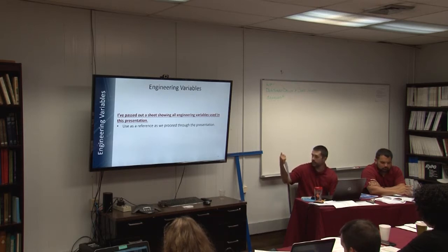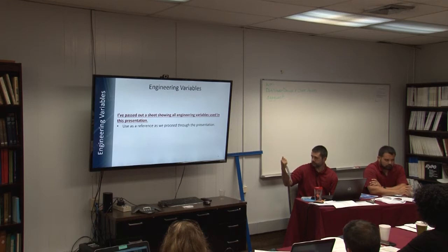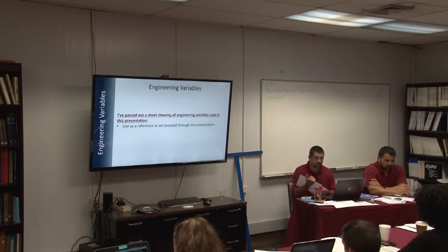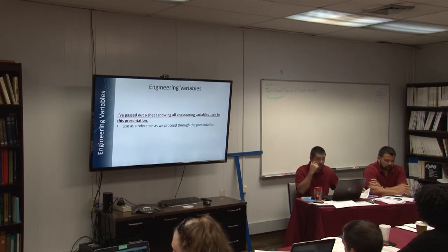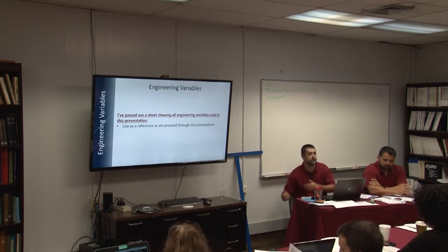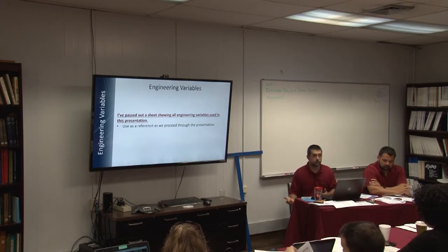PLS Tower is checking 6 limit states for you, and they're listed across the top. There is net section, rupture, and block shear. Those are tension limit states. Bearing and bolt shear are tension and compression limit states. And then buckling, or L over R, is a compression limit state. What we're going to focus on this afternoon is those 6 limit states, the calculations that the code requires, and how you get PLS Tower to do those calculations for you in the most accurate way possible.